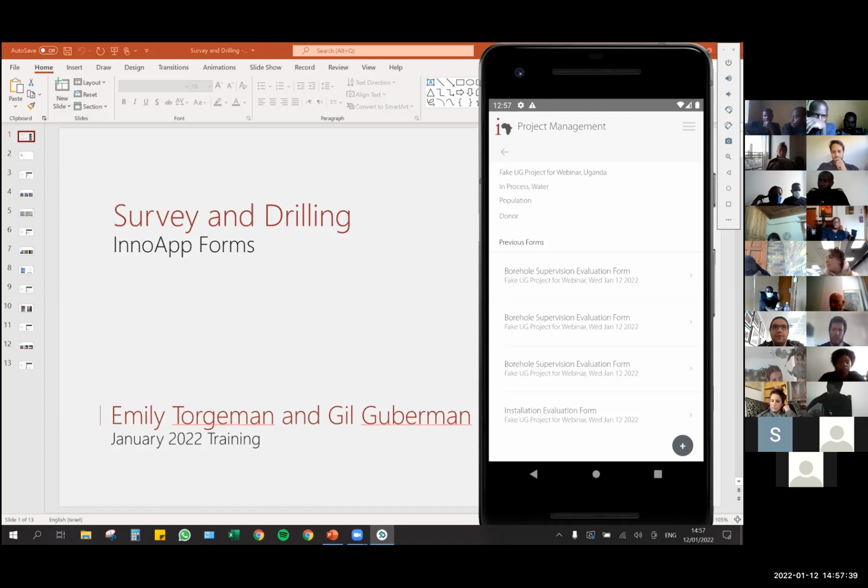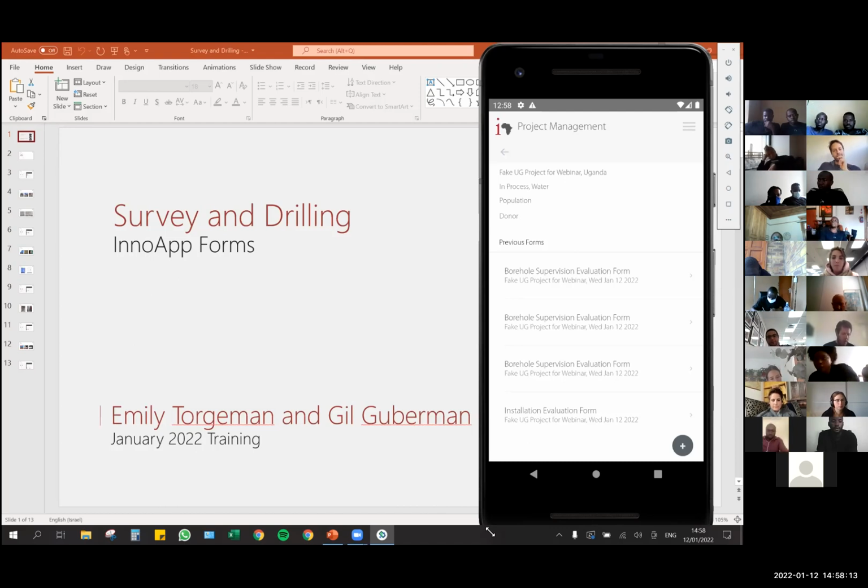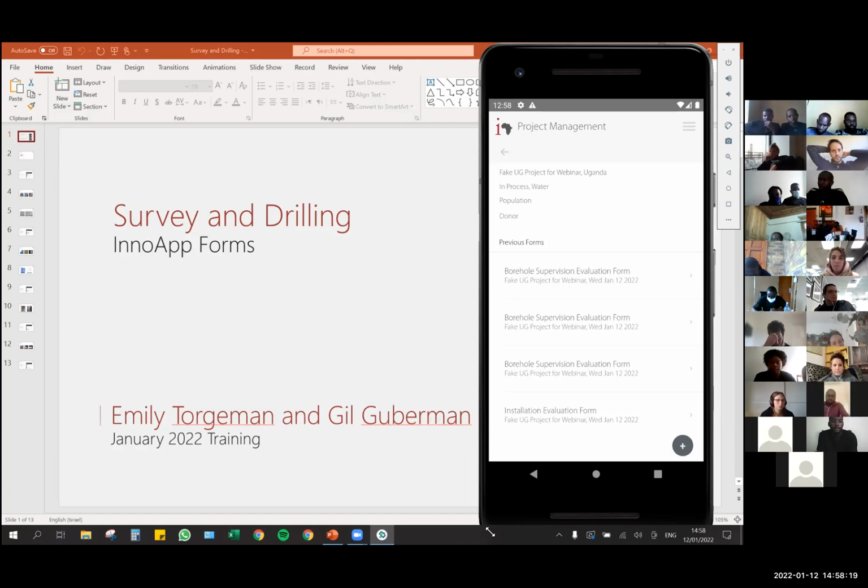New borehole, yes. And Mayan asked, are we not to move forward with a site that has less than 3 recommended points? Listen, that's a difficult question, because if there aren't 3 recommended points, maybe they didn't find 3 good points. We don't want to stop people from doing it, but we also really need to stop the situation where they find 3 recommended points and drill one borehole, the borehole comes back dry, and then suddenly they say that they need to do another survey and we have to pay for another survey.